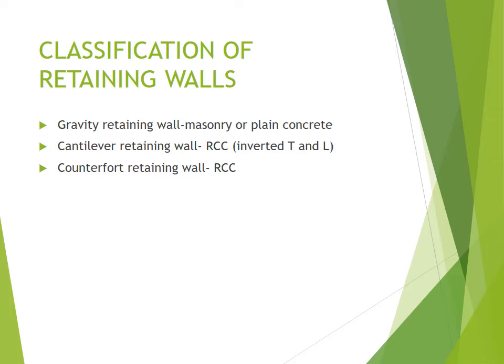Now, when you design this wall, you have to consider the height of the wall. It should not exceed 3 meters, because it only depends on the dead weight for strength. Over this height, the thickness of the wall has to comply with the safe height thickness ratio.